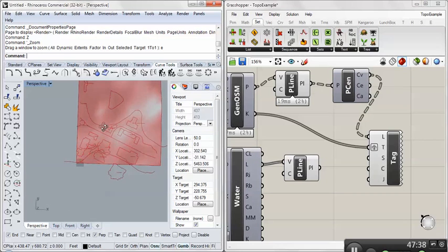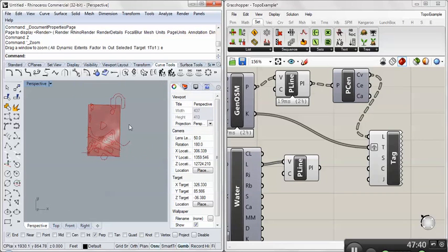the topography of the site. We have the data from OpenStreetMaps of all the buildings, the waterways, the roads. And so what are we going to do with this? So one thing that's often helpful is making a model of the site when you're doing iterations with design going through, is to have that site with your site carved out. You guys have a few 3D printers here. You have a couple other options for fabricating it. We'll go ahead and make this assuming that we were going to put it into the 3D printer and print this out. So what you need to do is give some volume to this component so you can actually make it.